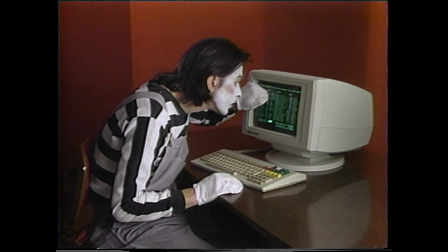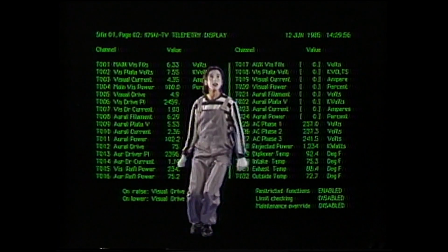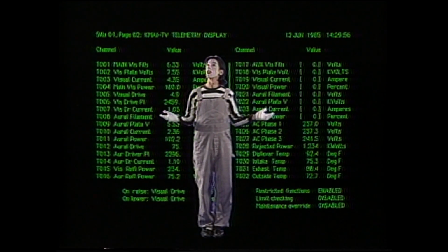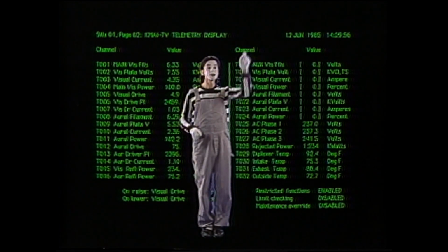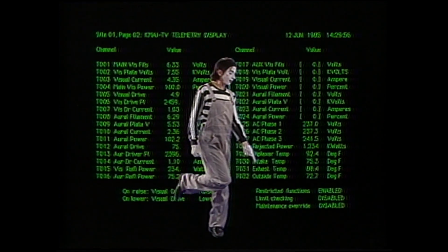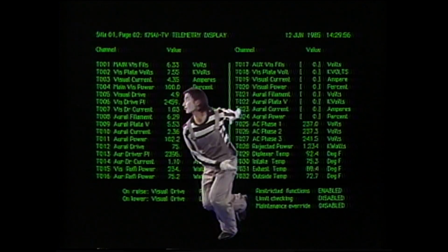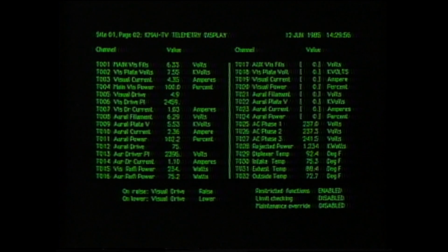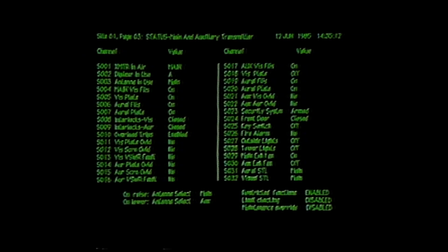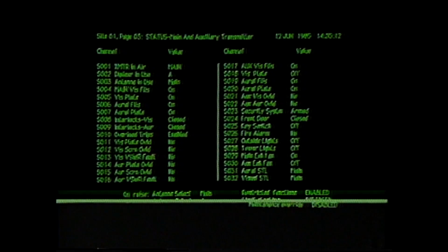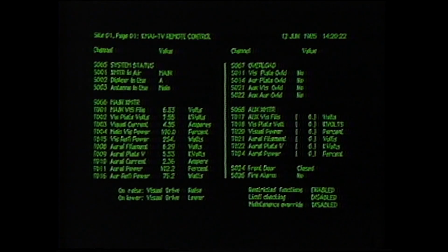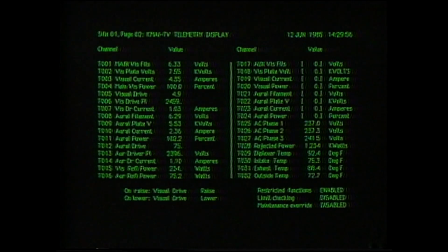Operation of the CRT option is straightforward. The basic display page shown on the CRT lists title, time, column headings, system status, and telemetry. Site selection is also indicated. Pages are organized to show telemetry, status, and command assignments separately. The master page may be organized by the user to include a mixture of vital telemetry and status parameters for a single site. Channel selection is indicated by a highlighted line.